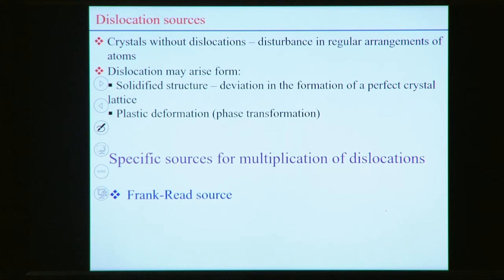So there are several ways to introduce dislocations into the crystal structure, and when you form a material through any kind of manufacturing process, for example melting, solidification, or metal forming processes, the material is always subjected to some amount of dislocations, or to the motion of dislocations.